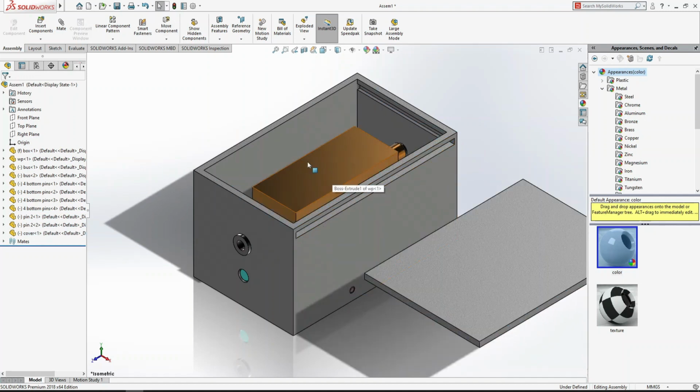Our workpiece will be put on the box. Then these 2 and 2, 4 and 2, 6 pins will be put in the box. Then we will put this workpiece, and this bush will guide the drill bit to make the hole on the workpiece. So that's the box jig that we have done in this tutorial.